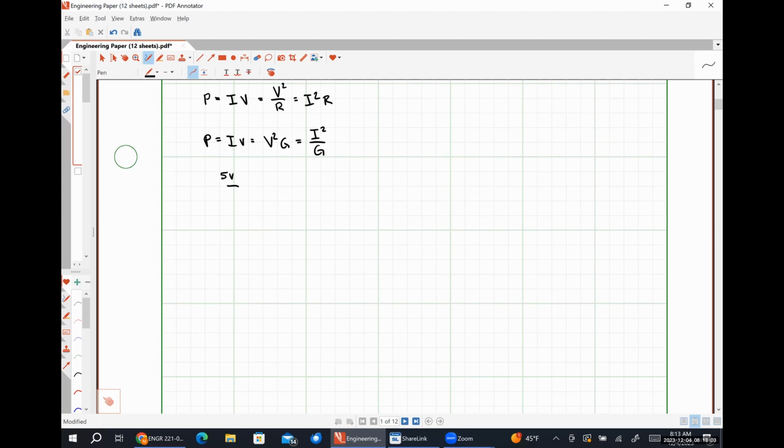a 5-volt supply from your Arduino. So this was actually probably one of your digital output pins that you were commanding to be at 5 volts, connected in series with a resistor. By the way, if memory serves me correctly, this would have been either a 220 ohm resistor or a 470 ohm resistor. Anything larger than that, and your LED is kind of dim.